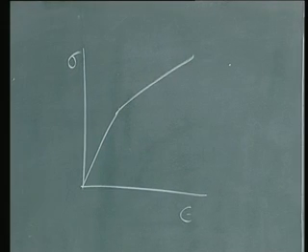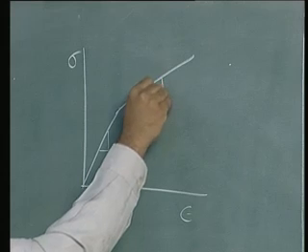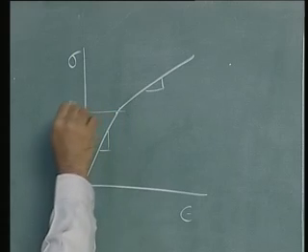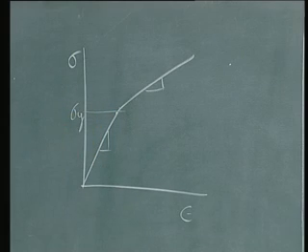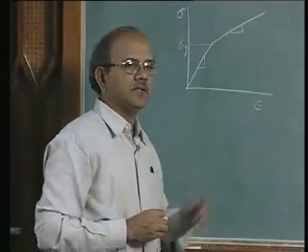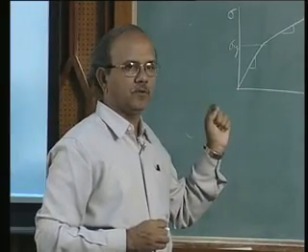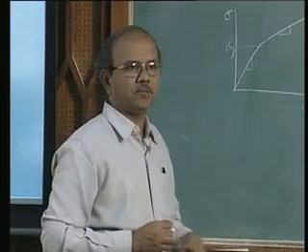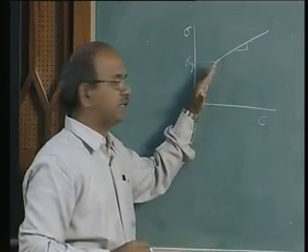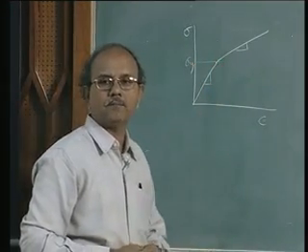where there are only two slopes that operate, and a well-defined yield point exists. Please note that this is a simple assumption. We can definitely modify it, and we are going to do that later. But in order to understand the issues, I'm going to look at this as a bilinear problem. I already made a lot of comments about the slope. This is exaggerated; it has to be very close to the y-axis and so on.